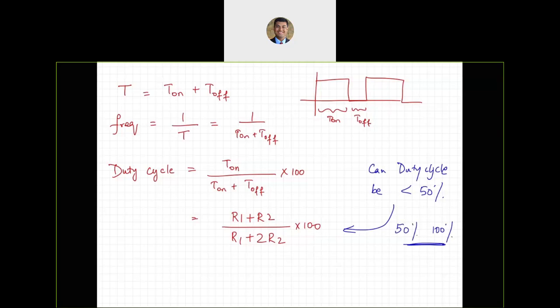to get 20%, what do you do? Well, you generate 80% and then use an inverter. You get 20% duty cycle. So feed the output of the timer chip into an inverter to achieve a duty cycle between 0 and 50%.